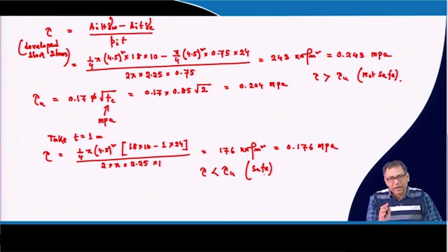So, there will be a shear between this seal concrete and the shaft. That is why we are checking that shear stress here, and there will be buoyancy also, which we have already checked. So, these two checks we have to do, and then based on that we provide the thickness of that bottom seal.